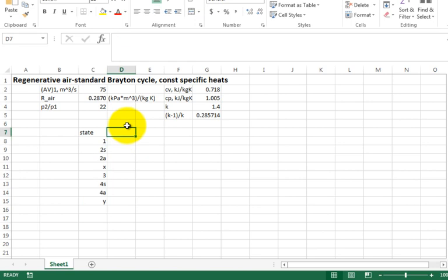All right. So pressure, I need to know that in kilopascal. I like to work that. Temperature in Kelvin, and we're using constant specific heats. I can put v, the specific volume, in meter cubed per kilogram. And let's percolate and put in what was given. In our first state, the inlet state, the pressure was 100 kilopascal and the temperature is 290. Is that true? All right.